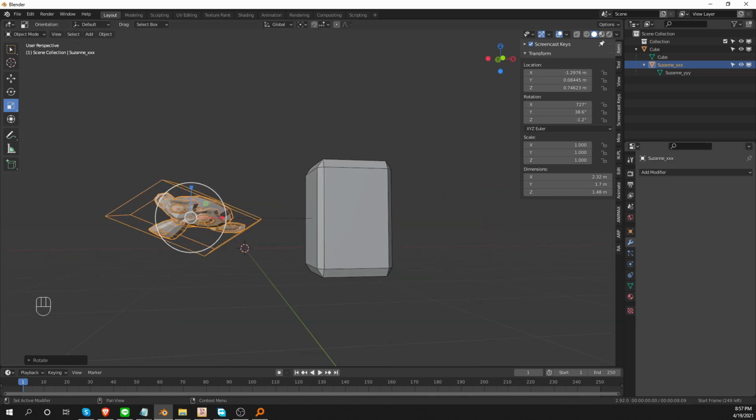When we first parented the two objects, Blender used something called matrices to offset the scale of the cube and to make things behave as the user would expect. And I almost wish that it wouldn't do that, because sooner or later things may start to break down. As you saw, when we scaled the cube after the parenting operation, things started to behave weirdly.